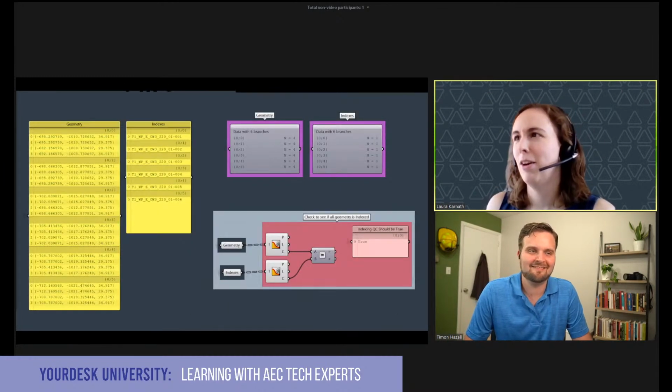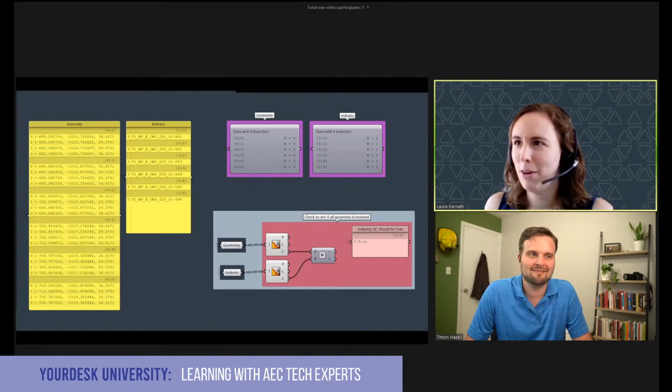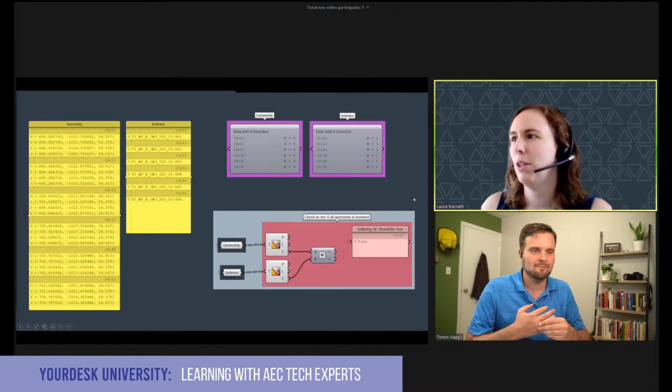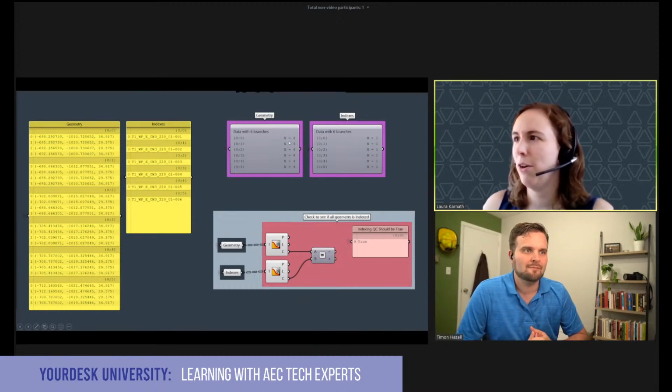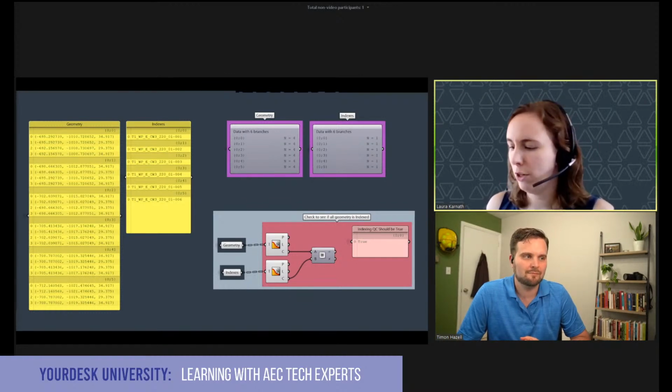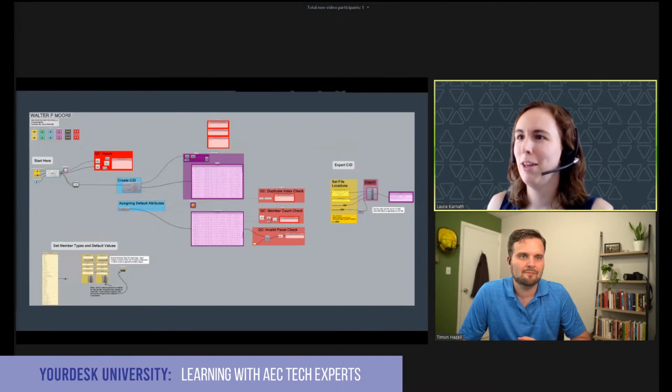It gets a little harder to do in the panels once you get to data trees, because now I have 4 corner points of a curtain wall panel and 1 index to go with that. Then you can start using the param viewer. In this case, it doesn't matter that there are 4 here and 1 here. I can just check the tree statistics and see if they match. So this is one of my interoperability definition canvases. You can see it's got little red boxes all over it.